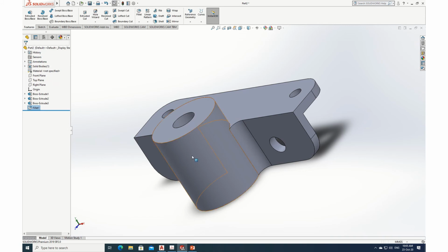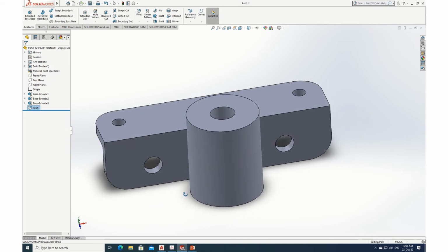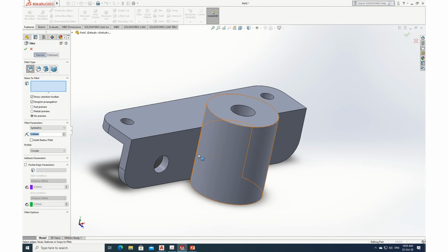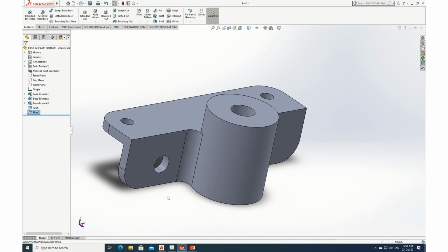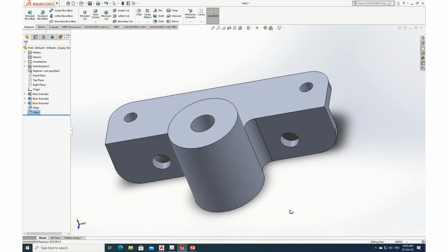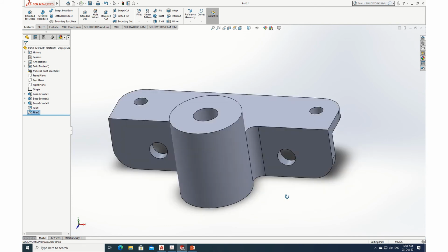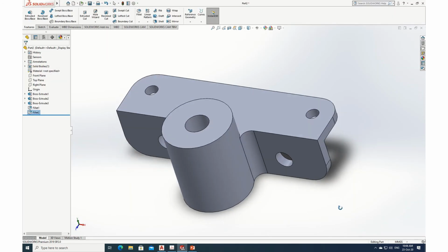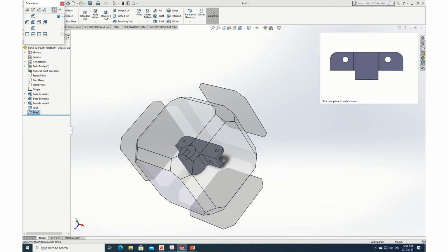Click. See, beautiful fillet is done. Now let's go here. Select again fillet. Where? This line. 5 only. Select. Okay. Done. Your complete picture is fully ready now. See here. Now let's go back how it is placed. It's placed this way. So now let's go back and place it that way only. So something like this.